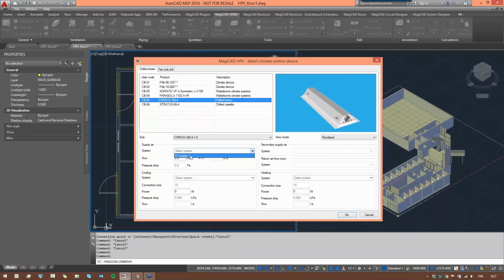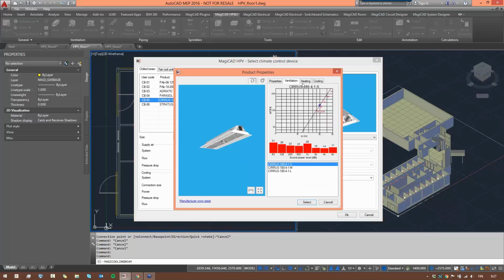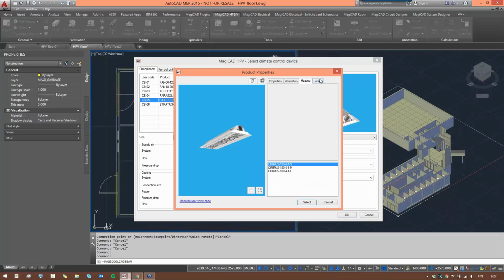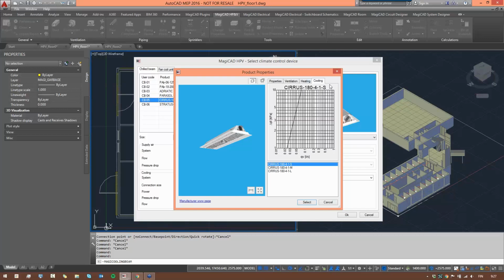So again, for this product, for chilled beams, first we need to select systems for it. Let's say 20 liters per second. Let's put two in each meeting room. Then the cooling systems and heating as well. Got to quickly check what kind of... there's no heating information here still. That's interesting.